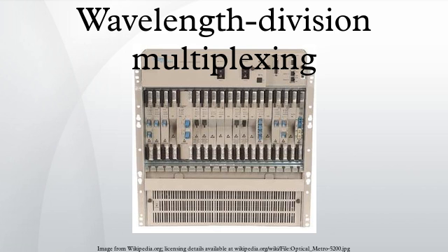ITU standards suggest that the OSC should utilize an OC-3 signal structure, though some vendors have opted to use 100 megabit Ethernet or another signal format. Unlike the 1550 nm multi-wavelength signal containing client data, the OSC is always terminated at intermediate amplifier sites, where it receives local information before retransmission.